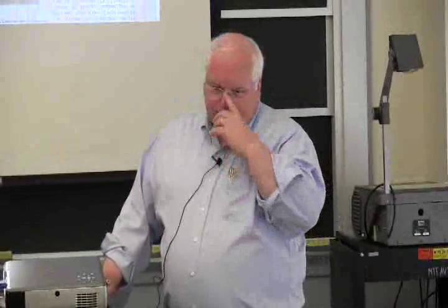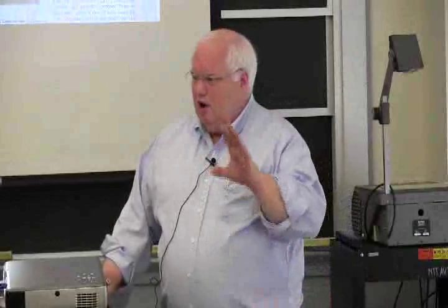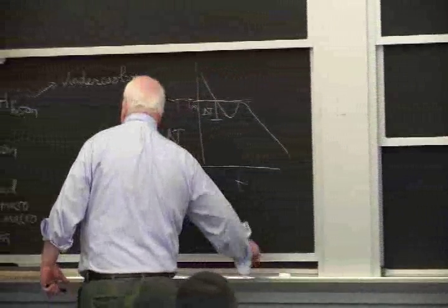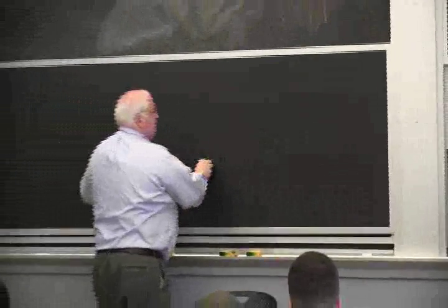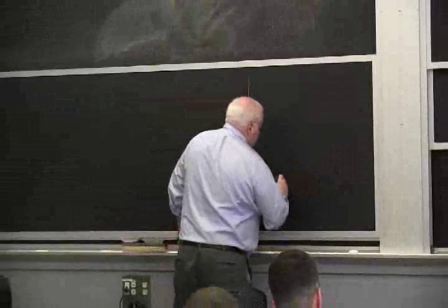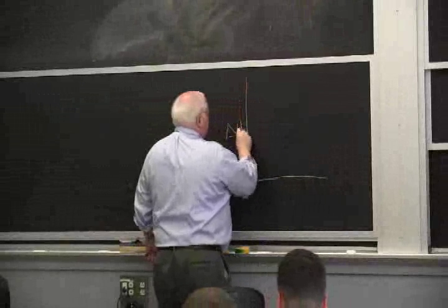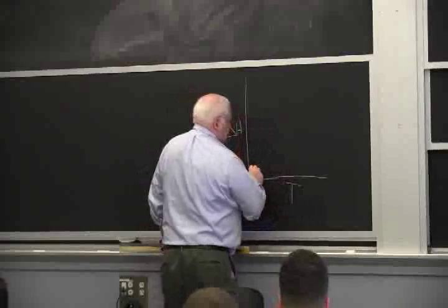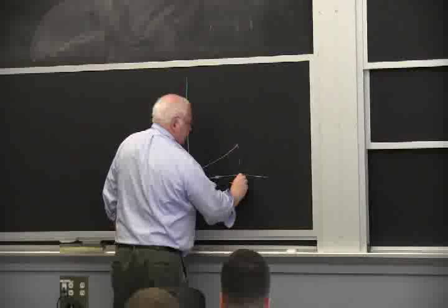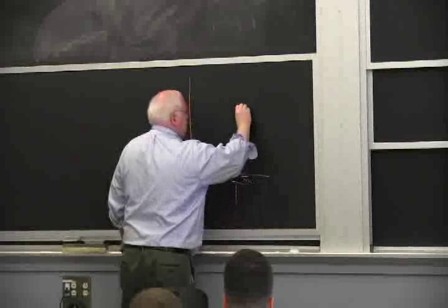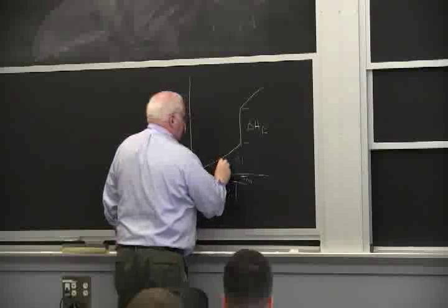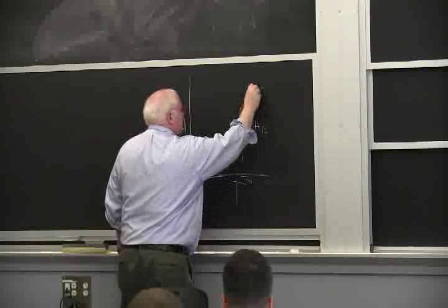25 years ago, people couldn't calculate. It was too complex a problem. The heat diffusion problem, where you have a step in one of the properties. For all you mathematicians out there, if you look at the enthalpy versus temperature, as the metal heats up, it gets to the melting point, and then you have this step. This is the enthalpy of the solid, and this is the enthalpy of the liquid.